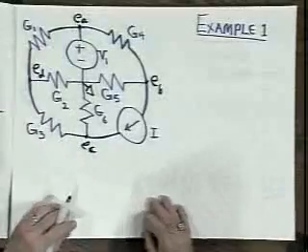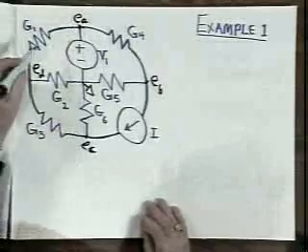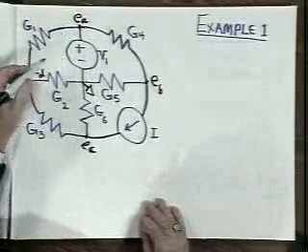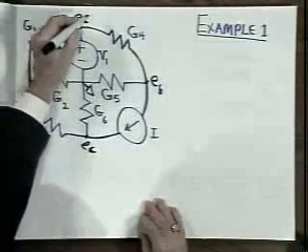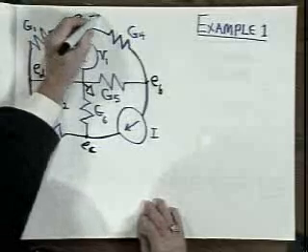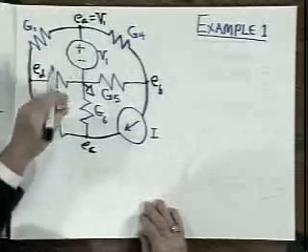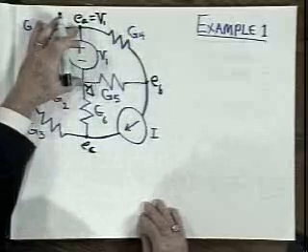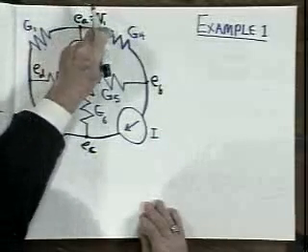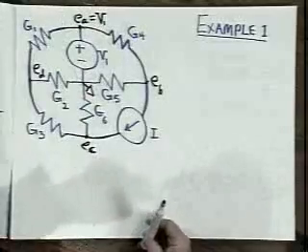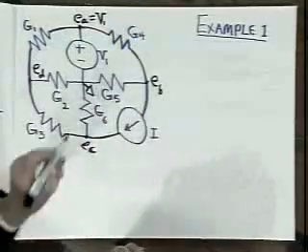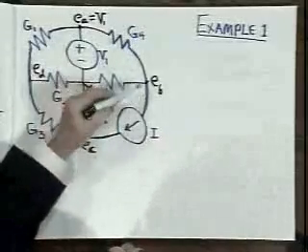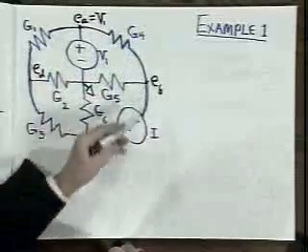Let's start by writing Kirchhoff's current law at node A, taking advantage of the fact that this voltage source constrains that voltage. So E sub A is equal to V1. The voltage source appears between the reference node and E sub A. So this voltage is fixed at the outset. It's not an unknown. I will write Kirchhoff's current law statements at these other 3 nodes and see what we get. In each case, I'm going to use the constituent relation for the element between the nodes to express a current. And I'm going to sum those currents to 0.